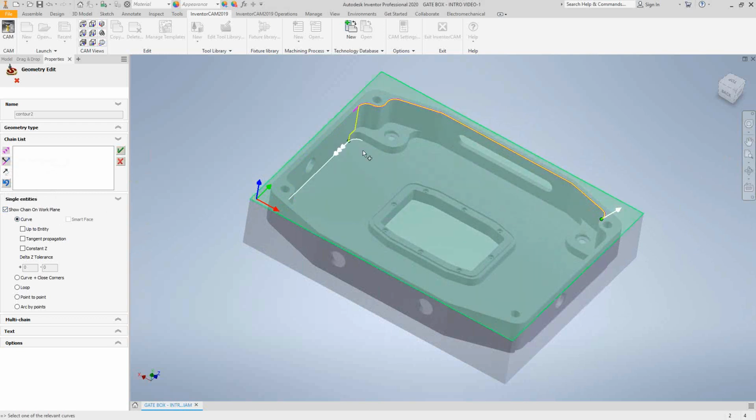So as you see, I'm going down, but it's projecting it to the tool plane. That purple line represents the tool plane. This is a prismatic toolpath, so I can go up and down in Z. I can choose any bits of geometry I want, as long as when they get projected to the tool plane, they look like a pocket. They're actually this planar guy here rather than the yellow.